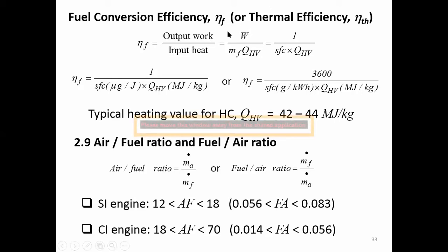One is the work, because this is always what we want from our engine. Another one is the heat, the input heat. In here, where does our input heat come from? The mass of the fuel times the heating value of the fuel. What kind of fuel we use determines the heating value. So this is the amount of heat input.